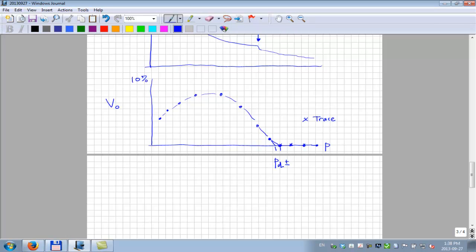It can be real. There can actually be a few of these little heavy molecules just dropping out, but they don't form together. There's not enough of them that you can quantify it. So there is something going on. Mother Nature is dropping some of those heavy components out of the gas into a liquid phase. Sometimes it's real, sometimes it's not. If that's the case, the dew point could be anywhere from here out to here, right?